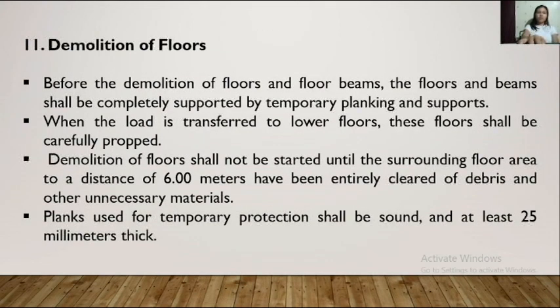Then we have also here the demolition of floors and floor beams. The floors and beams shall be completely supported by temporary planking and supports. Then the load is transferred to lower floors. These floors shall be carefully propped. Then the demolition of floors shall not be started until the surrounding floor area, to a distance of 6 meters, has been entirely cleared of debris and other unnecessary materials. Then a temporary protection shall be sound and at least 25 millimeters thick.